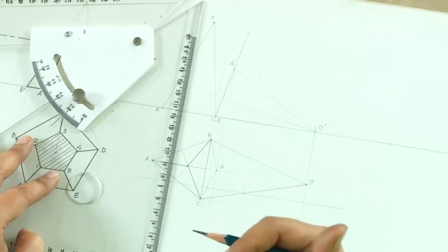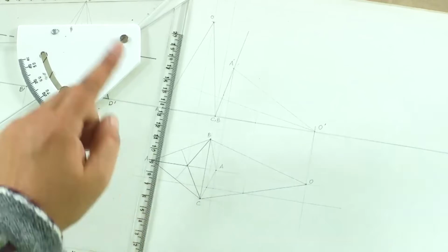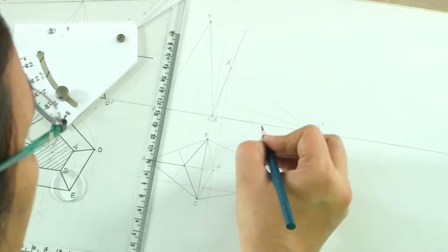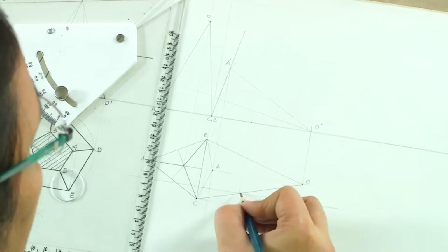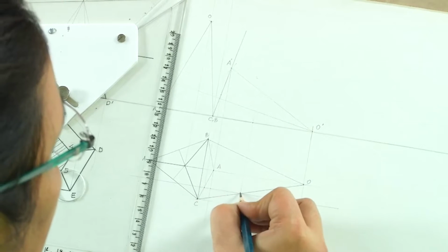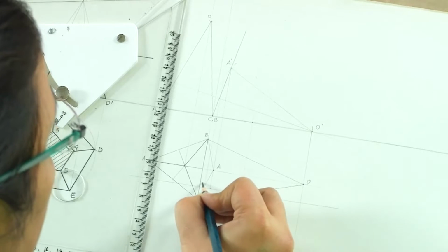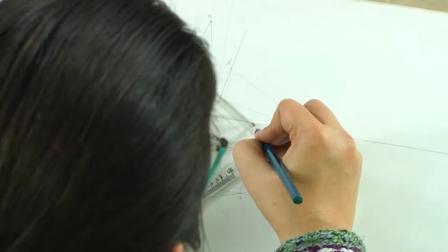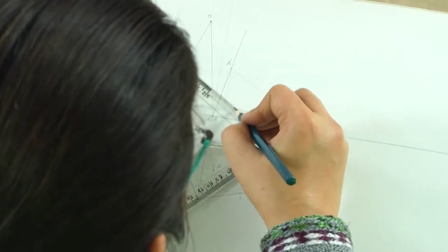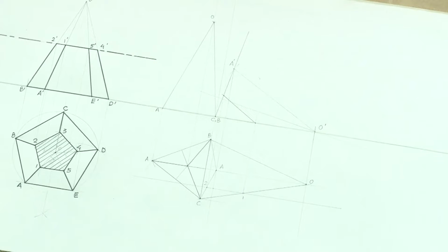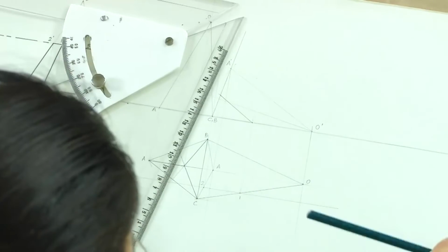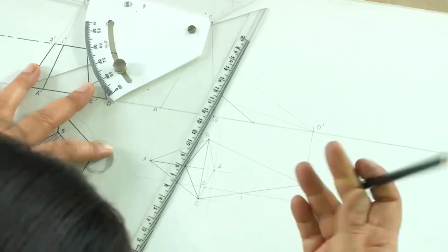If we look at this section, what happens? It is cutting only AC and OA here, and the next line, this A, and say it is 1, this is 2. So, this line is going to be joined. So, we will be joining this line here. There is nothing else which is getting cut there. So, what do we get as the true shape of this section here?